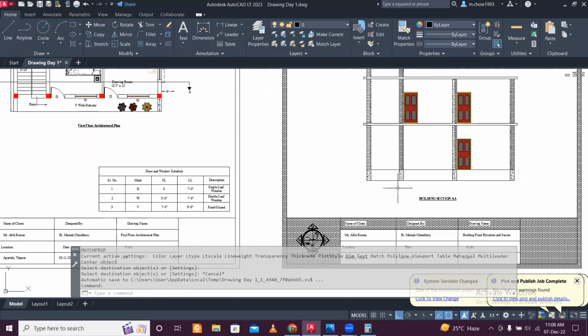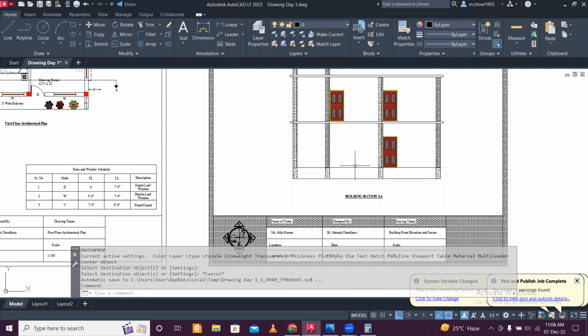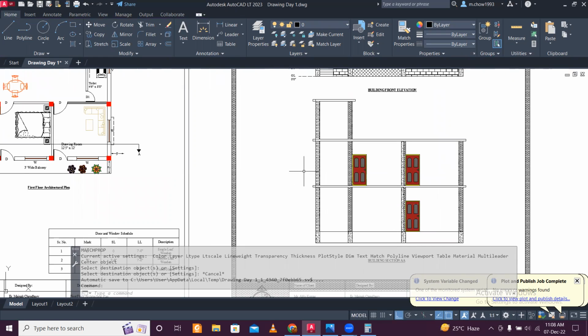And now in the bottom portion, we have sand or soil filling. So below the plinth level, we'll have to show the soil or the sand filling here. Now it may be asked that we'll also have the beams and all. Why don't you show the plinth beam? So you can show the plinth beam if you have the structural drawing with you, but generally in the elevation we only show the roof slab and don't show the beams.